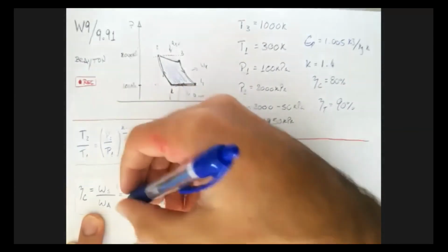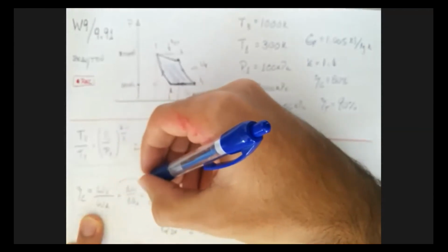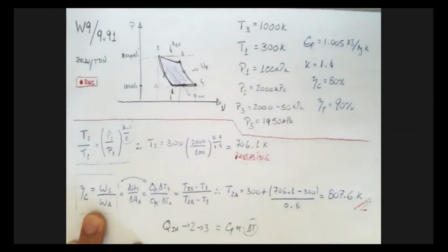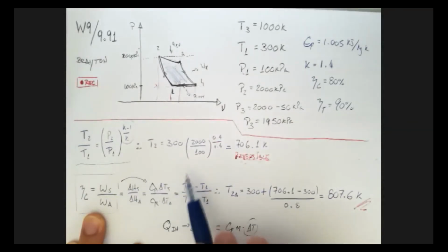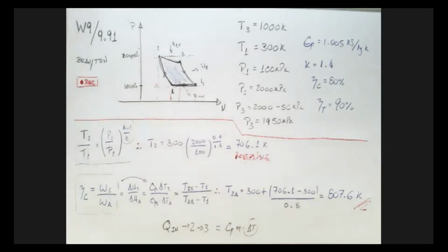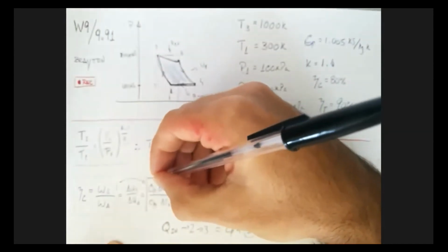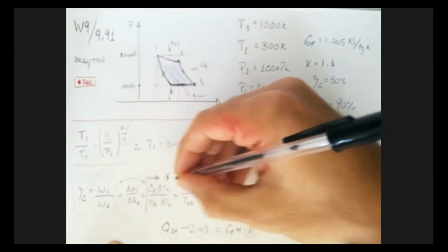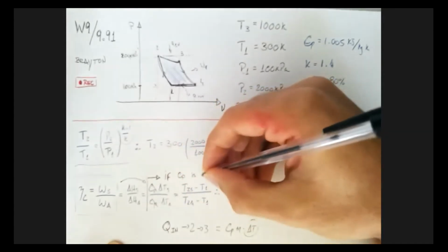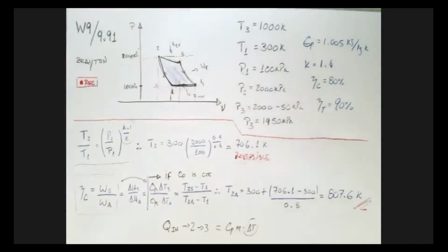But this part here, when we do this transformation, it's only when Cp is constant, right? Because your entropy is going to be changing from here to here, and if you cannot use the Cp as a constant one, you would have to take it from the tables, right? So from this part onwards, it's only if Cp is constant. Okay?